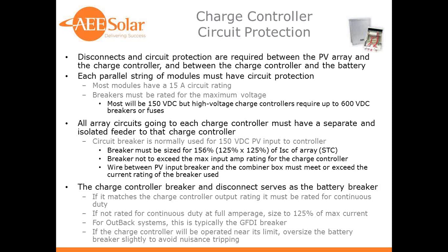There are a few controllers out there that you can actually gang up together on the same array. Midnite's Kid controller, for instance, you can use. It's a 30 amp controller. You can use 2 of those to get 60 amps on a single array. And some other controllers are starting to design those into their systems too.